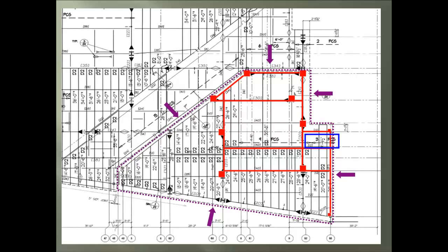With understanding the bundle callouts, how there could be individual sheets within a bundle, and knowing how to read the start and stop arrows, you will have a good foundation built to make sure the field installation is complying with the design drawings.